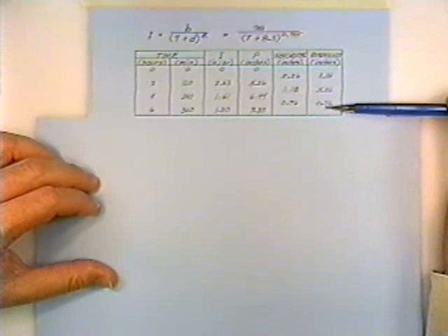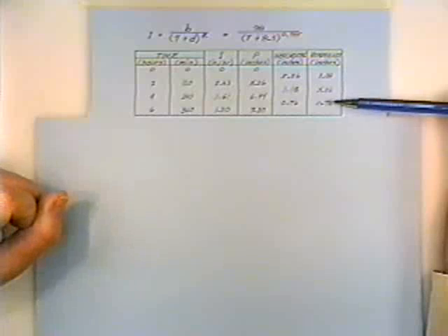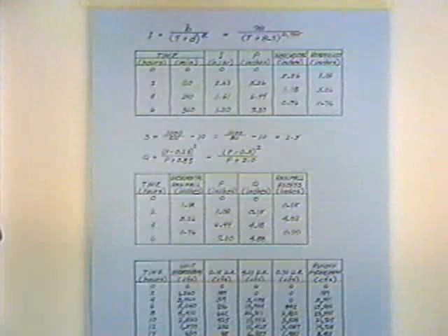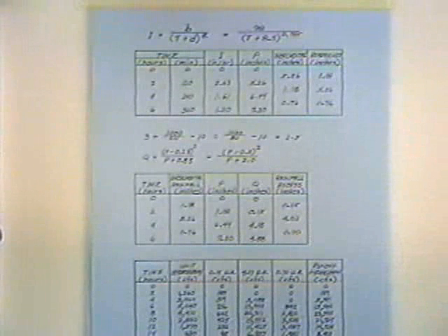That's called a balanced triangular rainfall distribution. A lot of textbooks will call that an alternating block rainfall distribution. There are other ways of doing rainfall distributions. So in our hypothetically, computationally created 50-year recurrence interval design storm, that's how much it rains in each 2-hour increment of time.